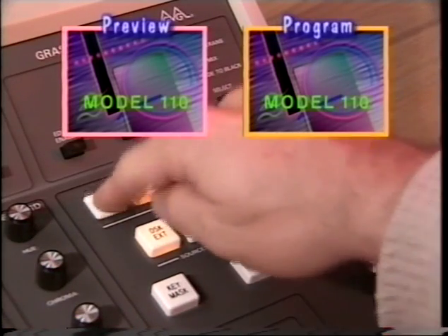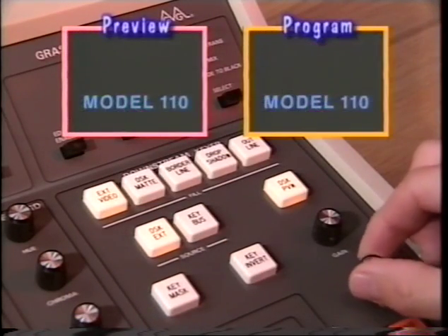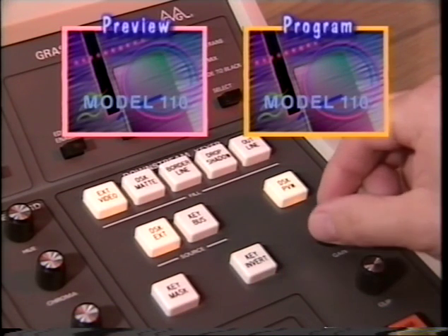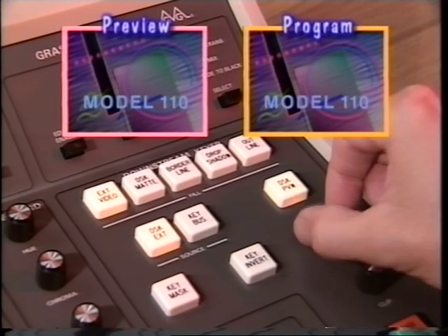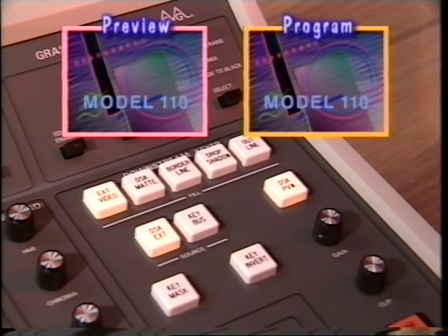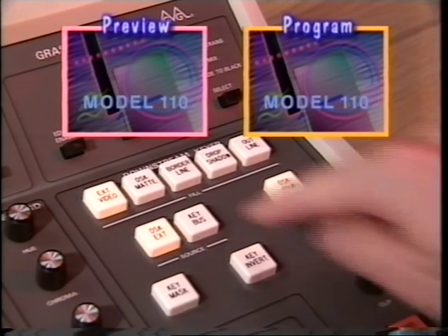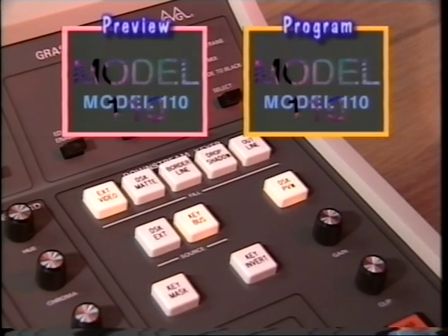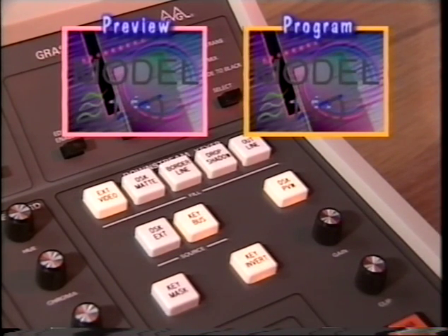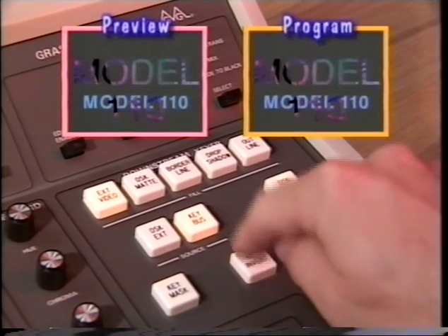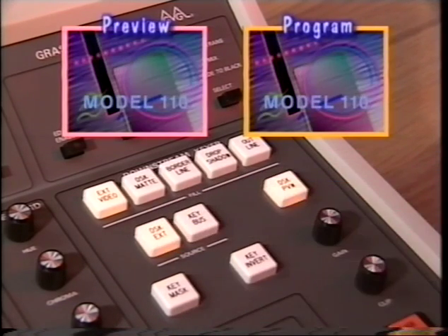Adjust the DSK clip and gain controls for the best key. If you are keying from a character generator with anti-aliased fonts, set the gain control to minimum to achieve a linear key with no jagged edges on the characters. If the selected source consists of dark letters or graphics on a light background, also select Key Invert for the best effect. The automatic key memory feature of the Model 110 also applies to DSK applications.